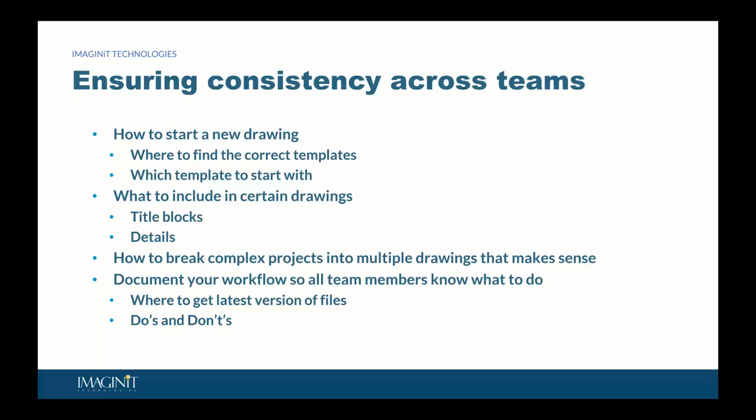Very good question: migrate catalogs or reuse from year to year. If you're talking about your part catalogs, generally speaking, you can reuse those year after year unless there is a significant change to pressure networks or to gravity networks. You will find that out when you get the new version installed and start kicking the tires on it.